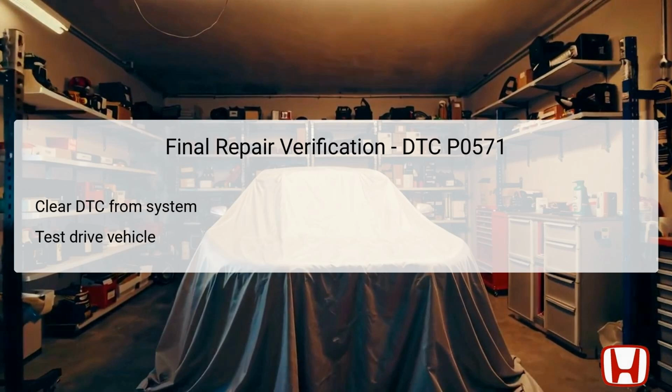Following the clearing of codes, it is imperative to conduct a test drive of the vehicle to ensure all components function as intended. Performing this drive will help validate whether the brakes engage properly and that the lights operate as expected under various conditions. If the DTC does not reappear and the system operates smoothly, you may conclude that the troubleshooting and necessary repairs were successful.